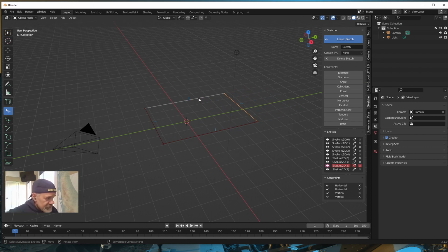Okay. If I select this one and drag it, I can only move it in this direction because there's a constraint tied to it. Okay. Now you can hover over and delete the constraint if you wanted to, and then you can move that line in any direction. All right. But that's what those little tags tell you, what kind of a constraint is tied to the line.